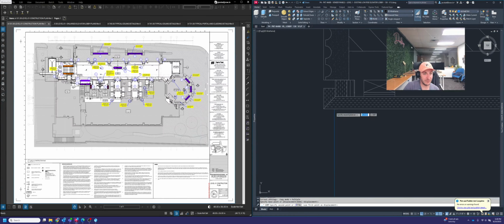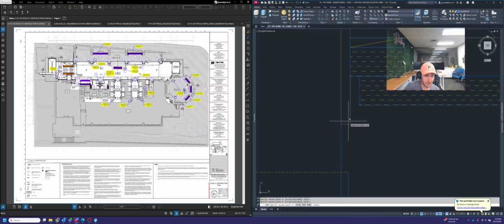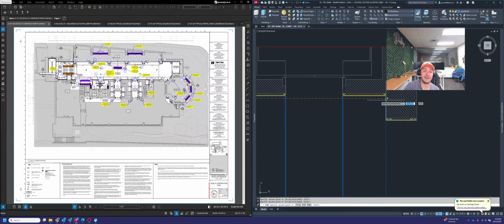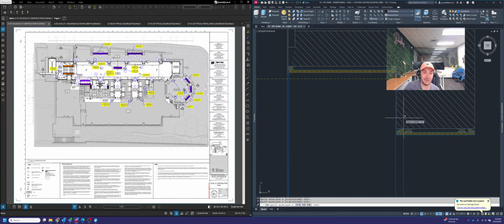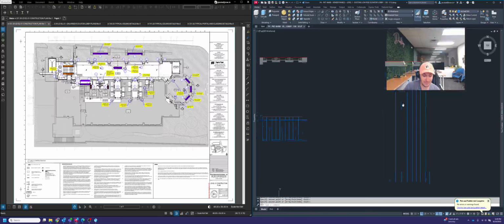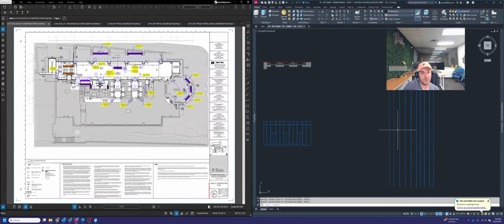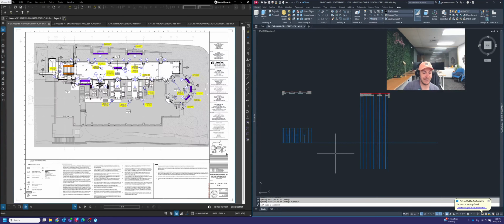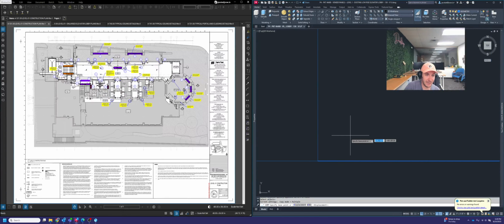But yeah, really important: always make sure to use those construction lines. It's going to help you make sure you're accurate in your drawing and that everything turns out exactly how it's shown from one view to the next. Now from there, because we have our elevation view over here on the left already drawn, we can draw construction lines off of that elevation view to get the heights. It's a neat way to do that because once you draw one, it makes things go way faster for the other one.